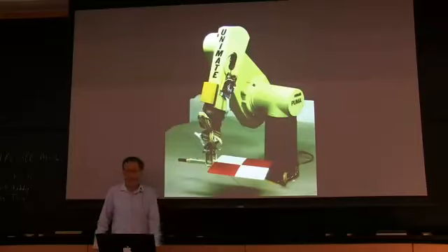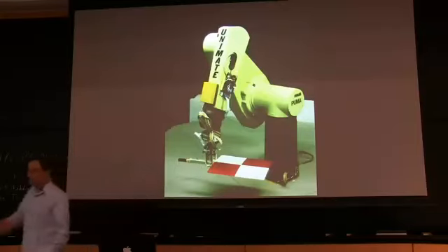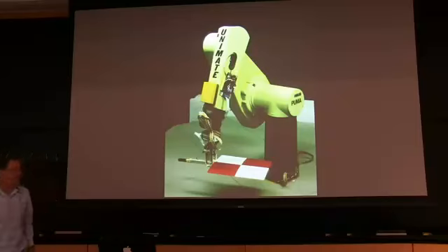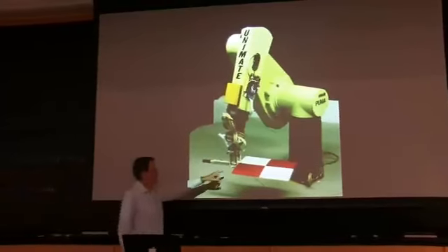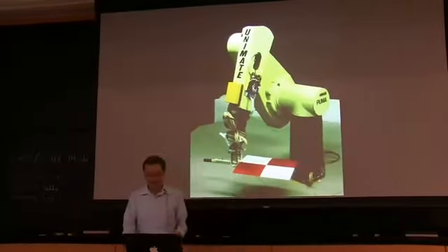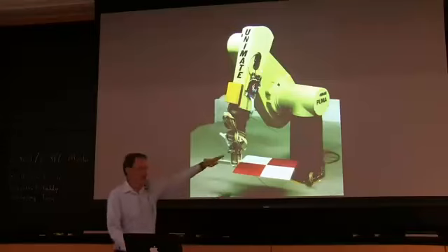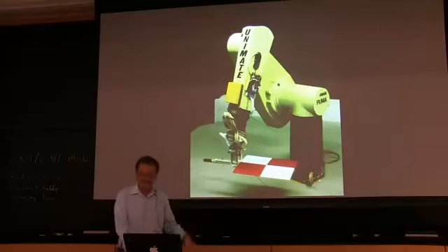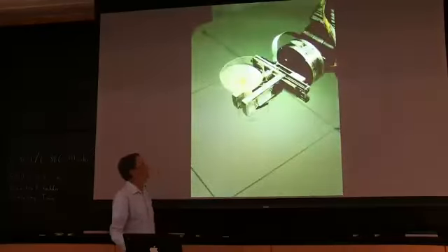This is something called a surveyor's mark, because surveyors have used that trick for a very long time. It's easy to process the image, and you can find the location of the intersection of these two lines very accurately with sub-pixel accuracy. So you move that around in the workspace and then fit a transformation to it, and then you can use that to